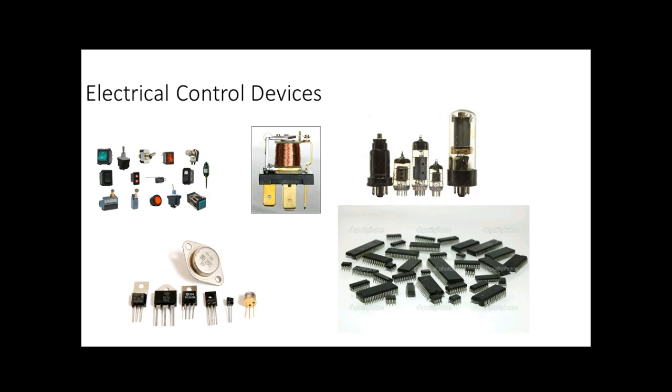So what this allowed us to do is in circuits like computers, where we're dealing with logic or ones and zeros, those ones and zeros can be represented with almost no current at all, because we usually use voltage levels, which means the size of the valves could become extremely small. Which means now instead of putting one valve on a wafer, we can put thousands of them, and we put entire circuits on a single wafer inside a single package, and we refer to these as integrated circuits.